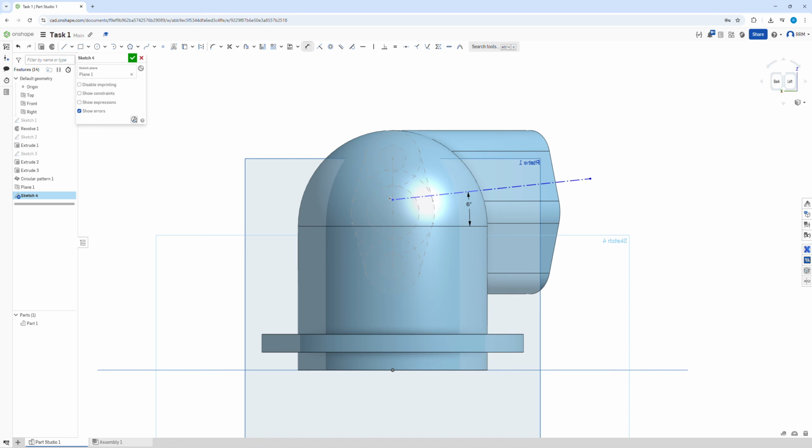That needs to be 6 degrees, like so. Okay, and in terms of height, we can have a look at that in a second, but we know we're going to be drawing a rectangle. So I go R. I actually want an aligned rectangle off that point. So aligned rectangle from here, draw it out. Oops, we don't want to be on the midplane. That's not going to work. Over to there, drag it up. Okay, that can be a random height for now.